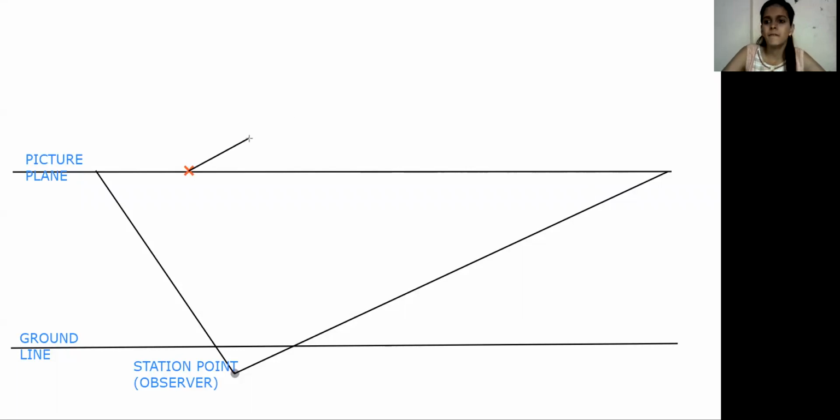So where we have taken the 30 degree angle, consider 3 centimeter only. Why 3 centimeter only? I'm showing it to you by calculating. We are drawing a plan. In plan, only tread is considered, because riser is a vertical portion and it can be shown in elevation or section or in a perspective. But in plan, we are going to show only the tread.